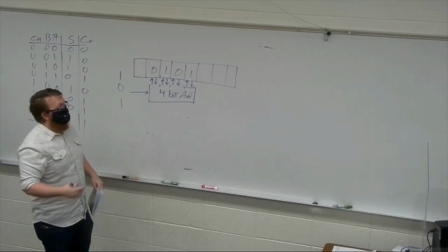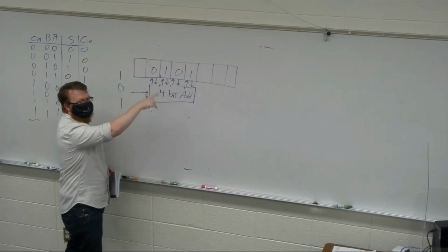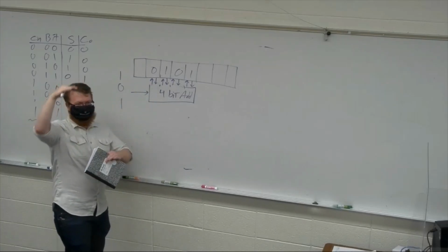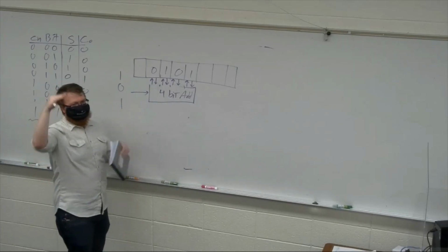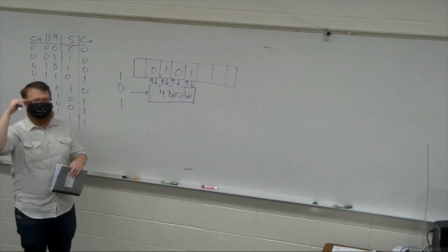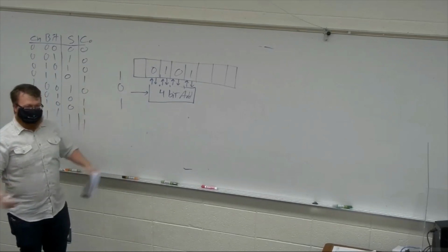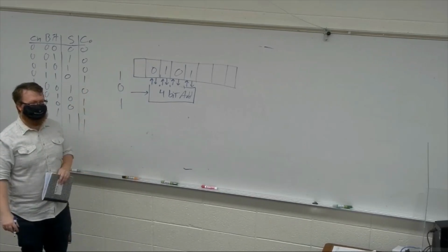And it only has to do that a couple of times, really the n bits, right, before you get the right amount. And because you can add each of these individually, right, so we went and created a stack of 3, and we went through and added all 3 up. This is just adding them one at a time, and that's why it's called an accumulator, because it's going to do each add at one step. So now all you need is an 8-bit buffer, a 4-bit adder, and a little bit of support logic.